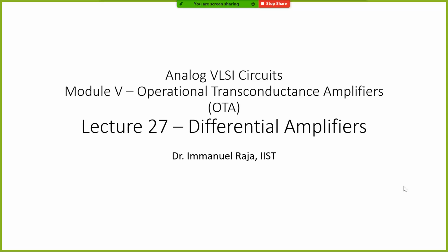Okay, so that brings us to the next module, which is the operational transconductance amplifier, also called OTA. And just in case some of you are wondering what this new long term is, if you add a voltage buffer to it, basically a common drain or an output stage, a class AB amplifier or something like that, it becomes an op-amp. An OTA plus a driver stage becomes an op-amp. And the reason why we call it an OTA and not directly an op-amp, we'll look at in one of the following classes.